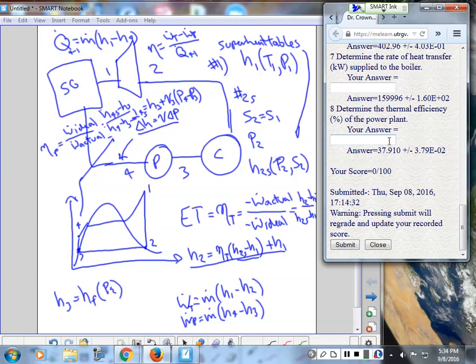The very first problem is just a Carnot problem where these are the four states. This is the inlet to the turbine, this is the exit of the turbine, this is the inlet to the pump, and the exit of the pump. The problem is that will tear up your turbine, and a pump can't take a saturated liquid-vapor mixture. So it's impractical, but it does represent a theoretical maximum for these operating temperatures, because the Carnot cycle is a reversible cycle.